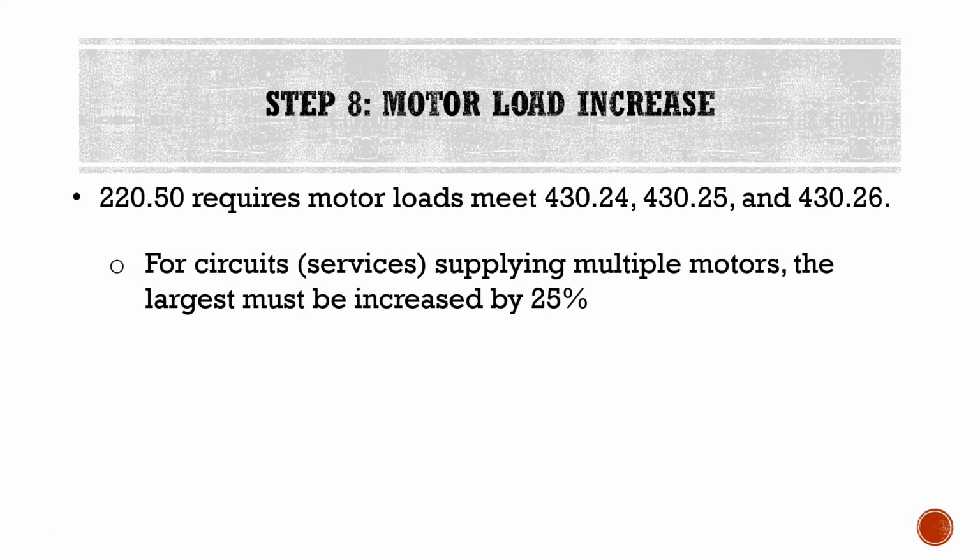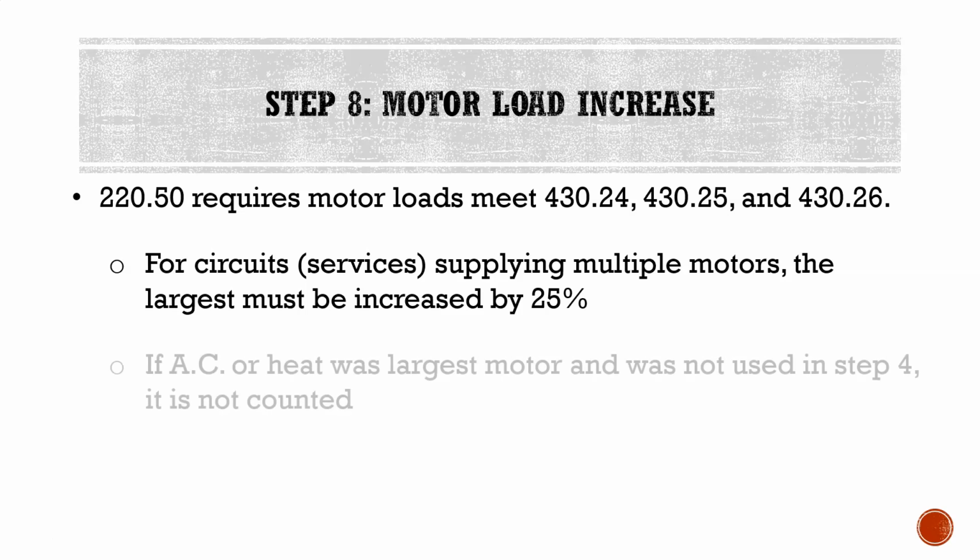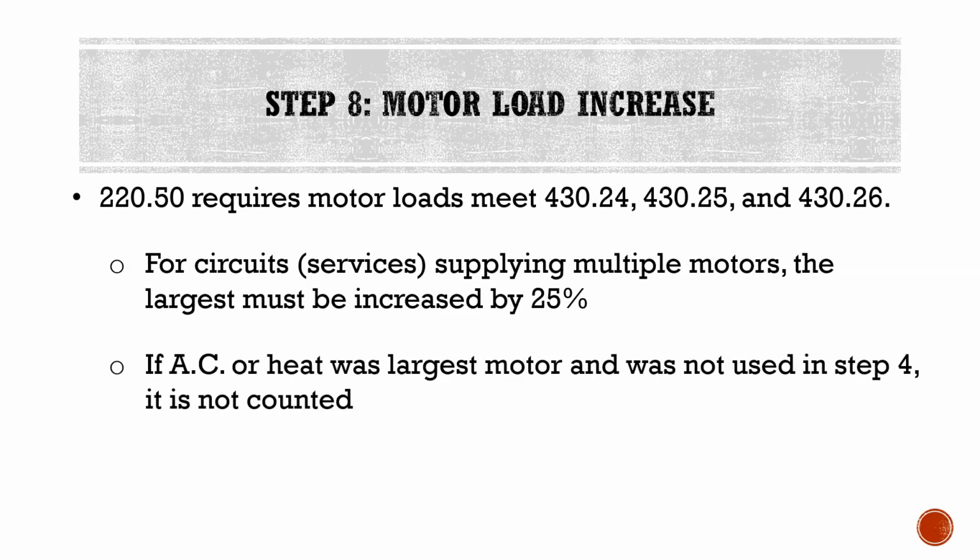So that's the idea that we're going to be looking for in step number 8, that our service needs to be sized at least 125% of the largest motor. Now, the first place I see people mess up a lot is, since you need to pick out the largest motor, they'll go back through the equation that we've done and try to find where the largest motor was. And more often than not, it'll be your AC load.